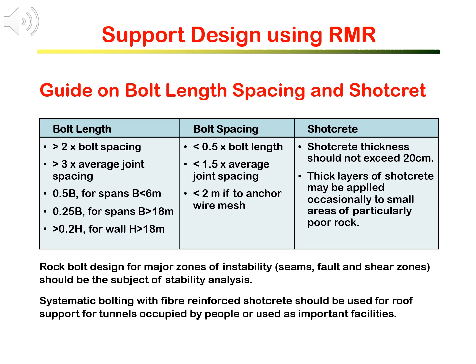In addition, rock bolt design for major zones of instability, for example, seams, faults, and shear zones, should be subject to stability analysis. In general, systematic bolting with fiber-reinforced concrete should be used for permanent roof support that will be occupied by people or used as important facilities.